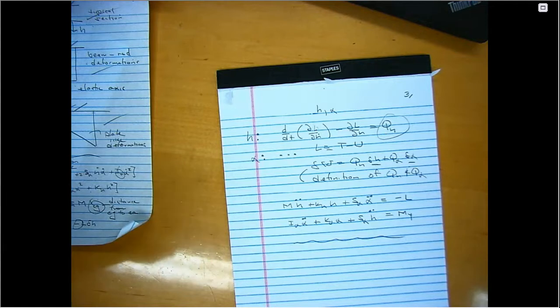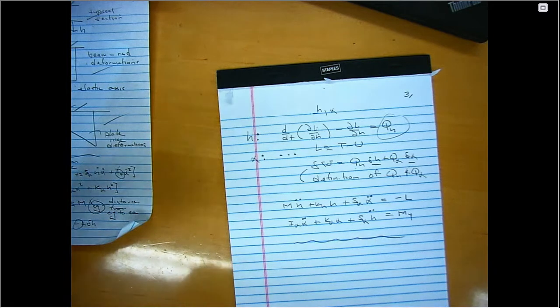In practice, that's not a sensible thing to do. You need to choose a structural model and an aerodynamic model that are roughly comparable in their level of physical fidelity. There's no point in using a very elaborate structural model and a very simple aerodynamic model. That's what's usual. There are some exceptions.